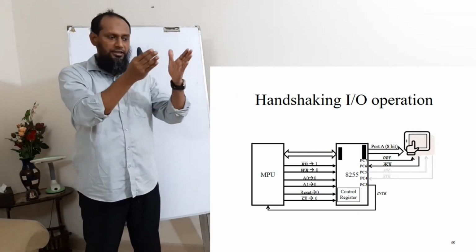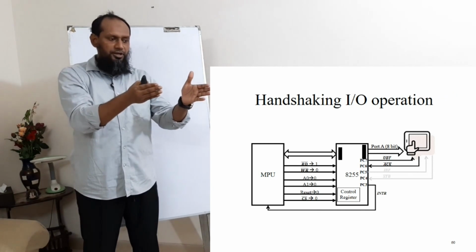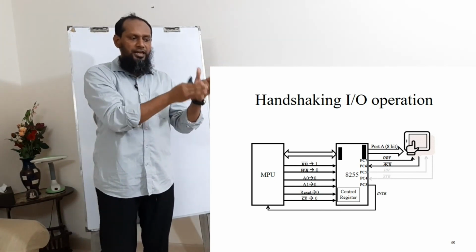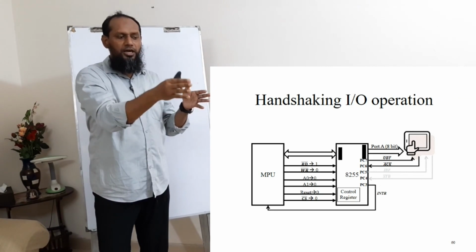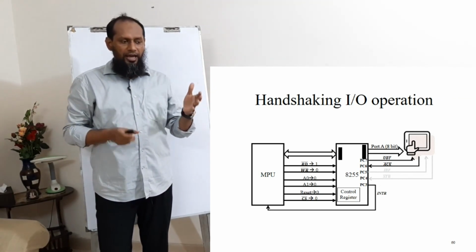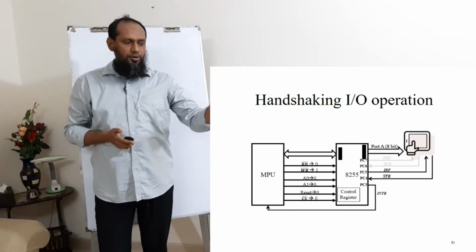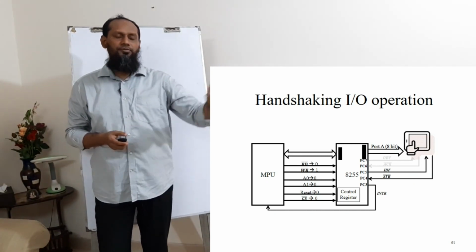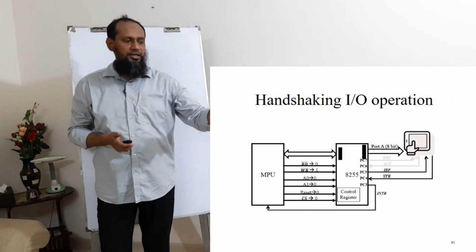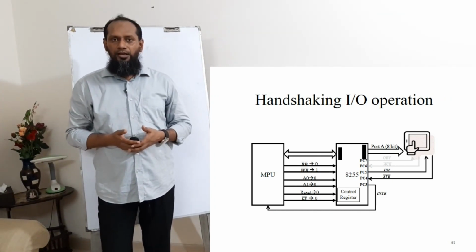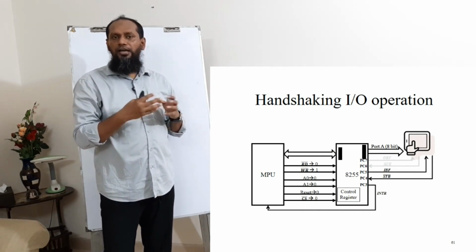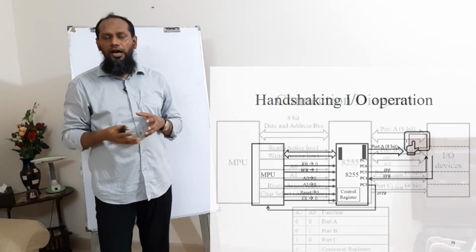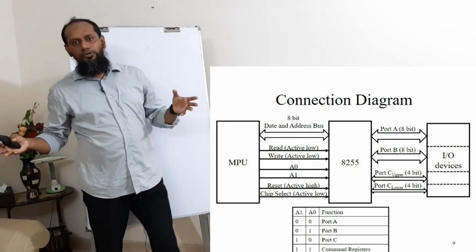No. You can see in this timing, first the MPU is sending some data from the microprocessor to the touch screen, and at this timing the microprocessor is receiving data from the touch screen by using PC3, 4 and 5. But for sending it was using 3, 6 and 7. I will give you the time diagram on your slide for read and write handshaking for bidirectional I/O operation.